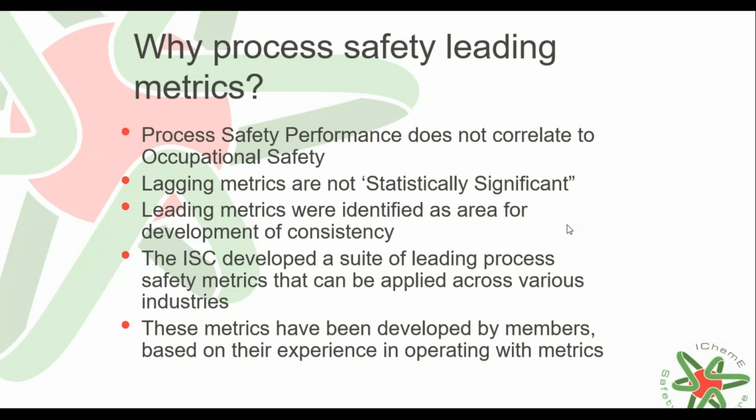Okay. So from a design perspective, you'll notice that there are lots of different types of PSVs depending on different applications, and making sure that you've selected the right PSV for the right service is really important.